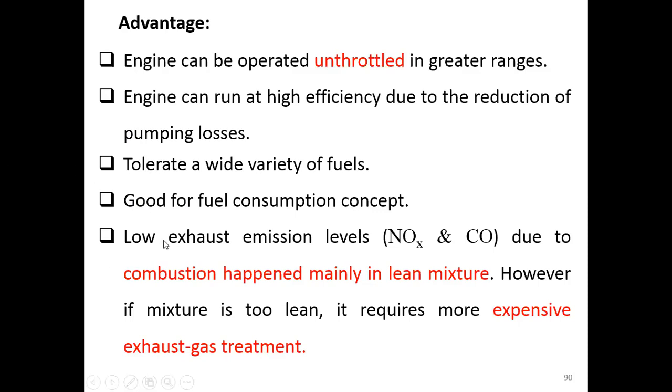And the good part is that it can provide a low exhaust emission level, both NOx and carbon monoxide, because the combustion happens mainly in lean mixtures. The rich mixture is near the spark plug region.